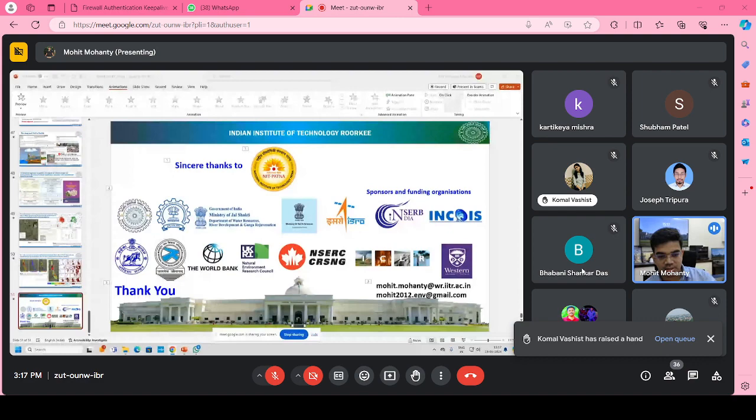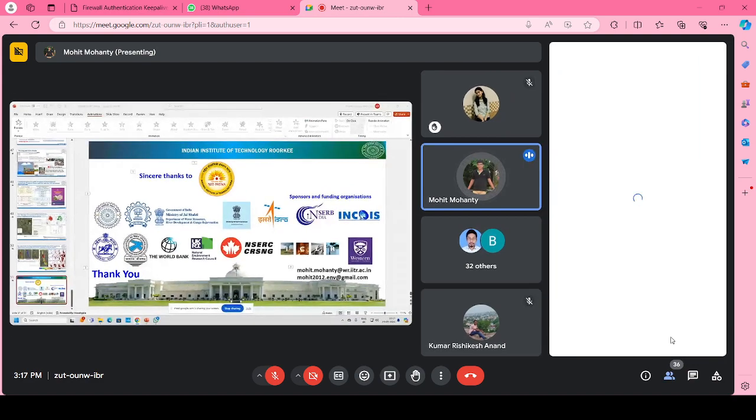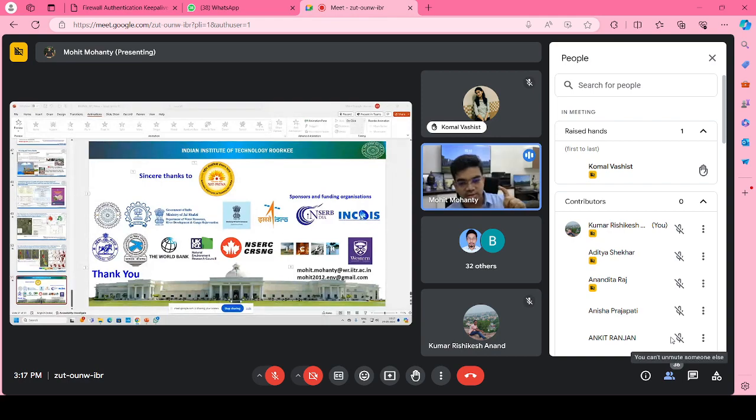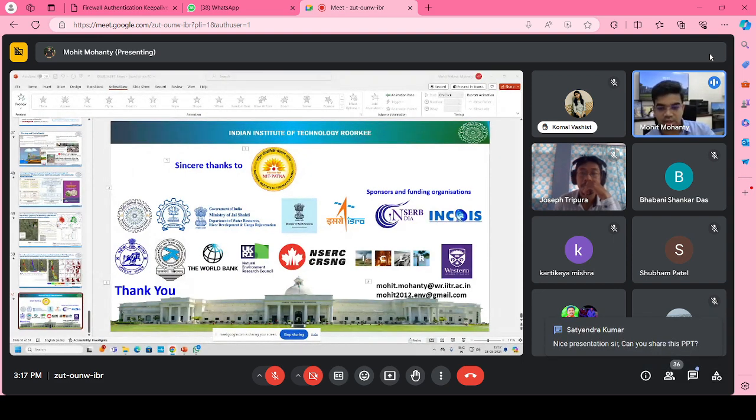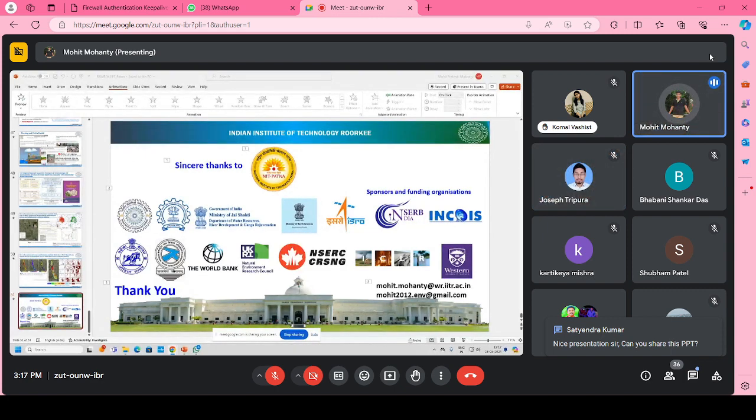In our work, we followed a criteria that was published sometime back for India. That was a standard based on the human height and how much impact it can have on the human height or the vehicles. Based on that, we had considered a standard that you can find in our paper published in the Journal of Environmental Management. That standard is a combination of water depth, the product of water depth and velocity. According to that, we say whether it is high hazard, moderate hazard, low hazard, and so on.